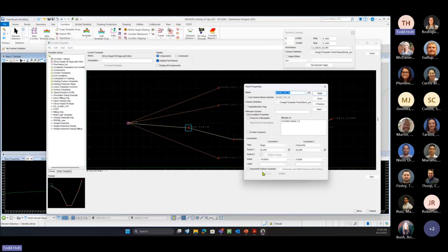So here, it's always going to draw to the constraints. So this from the slope to the berm top end is always going to be 8 feet and a negative 10% slope. If we want it to be dynamic, we can control the slope by adding in a parametric label or a horizontal feature constraint. Right, so we have those. But if we do a label, that's going to be our parametric constraints.